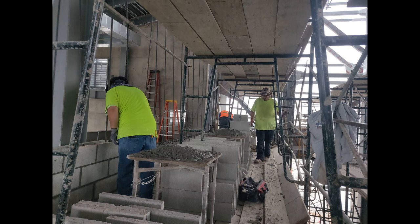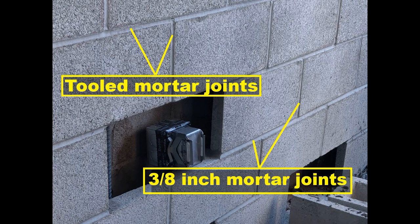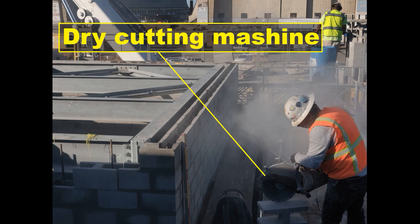Select units to be used in exposed masonry surfaces from those having the least amount of chipped edges or other imperfections detracting from the appearance of the finished work. Jointing. Tool mortar joints when the mortar is thumbprint hard. Tool horizontal joints after tooling vertical joints. Brush mortar joints to remove loose and excess mortar. Provide 3/8 inch wide mortar joints in concrete masonry.